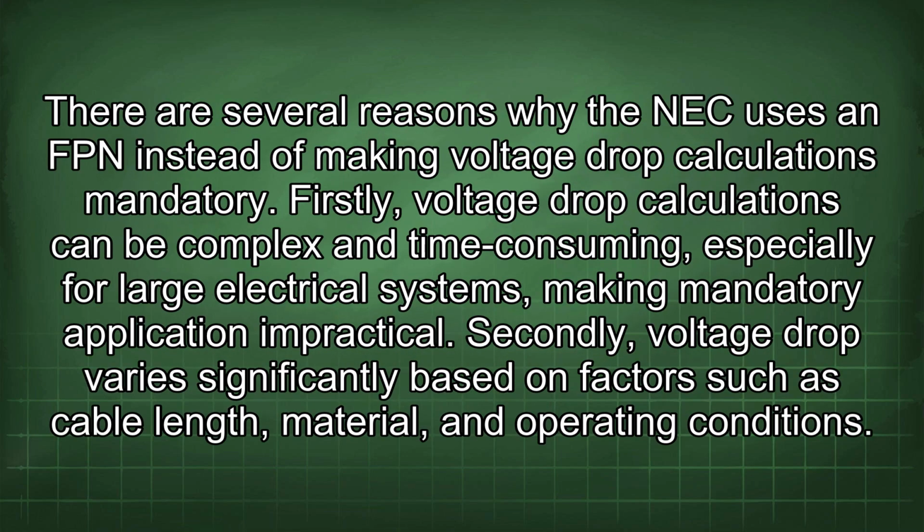There are several reasons why the NEC uses an FPN instead of making voltage drop calculations mandatory. Firstly, voltage drop calculations can be complex and time-consuming, especially for large electrical systems, making mandatory application impractical. Secondly, voltage drop varies significantly based on factors such as cable length, material, and operating conditions.